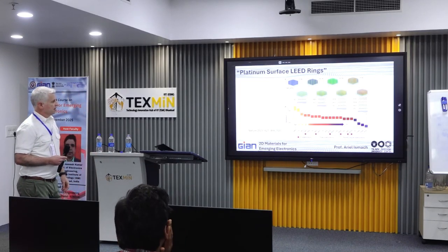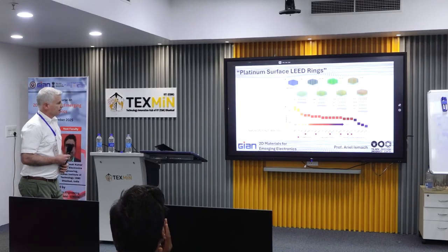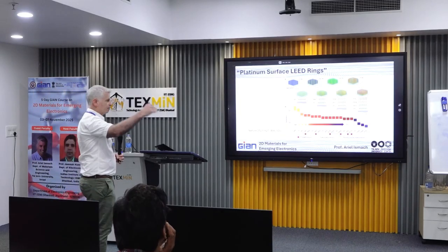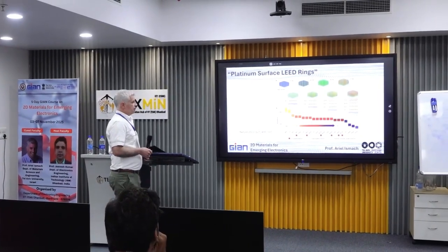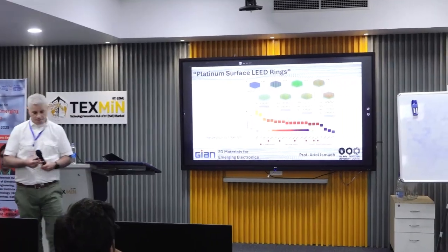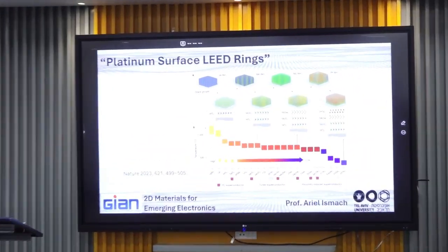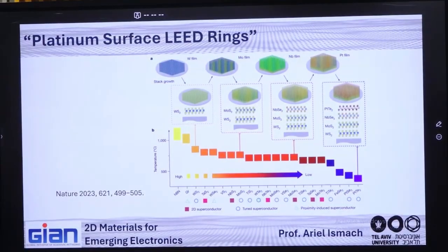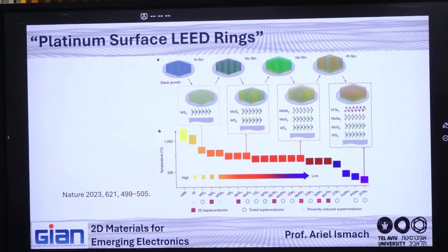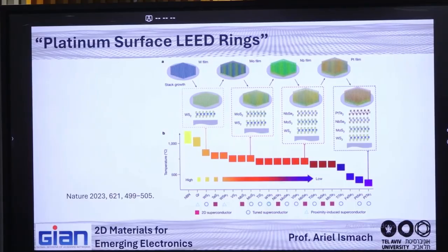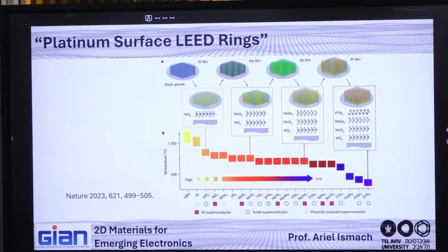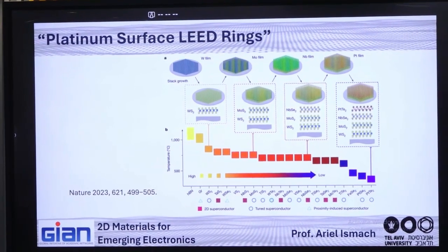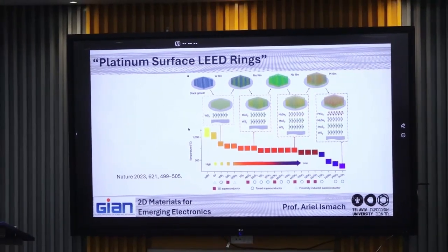So here you can see basically a sequential growth one after the other. And the way that they did that, actually they did a fairly simple growth in this case. It's not CVD, it's not MOCVD, it's just sulfurization of a thin film of metals. So they made very thin metal films on substrates by sputtering. I didn't talk about sputtering, maybe I should have talked about sputtering.